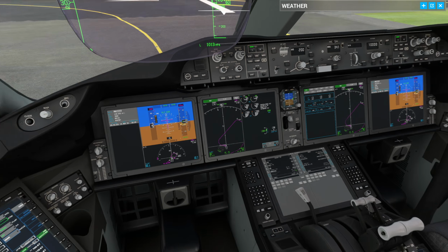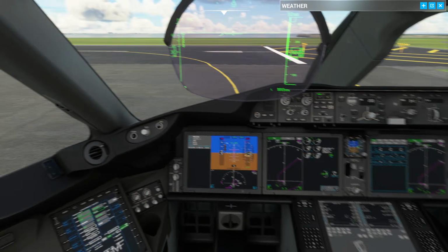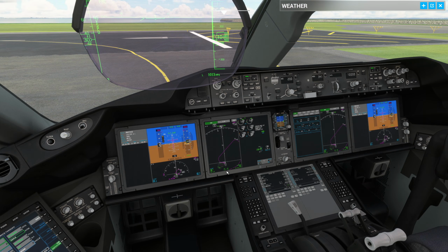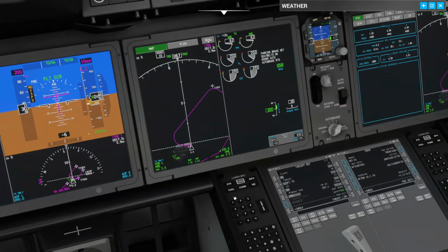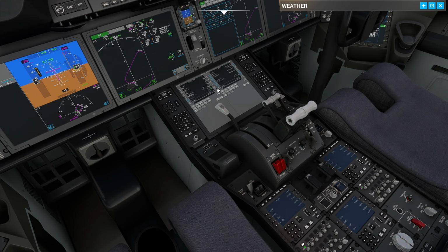So can you imagine that? You've taken off, you've lost an engine, and now your other engine's depowering in order to make sure that you can keep the airplane under control. Now that's an extreme scenario. It's not likely to happen if you have an engine failure, but it could, and that's why Boeing has added that system in. And it's particularly likely to happen if you were to add full power.